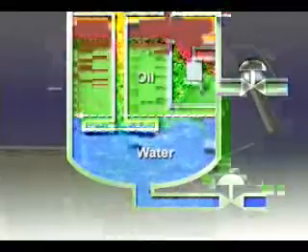From this point, as the oil rises, any free water separates out from the oil phase. The water droplets flow countercurrent to the oil. Similarly, the water flows downward, and oil droplets trapped in the water phase rise countercurrent to the water flow.